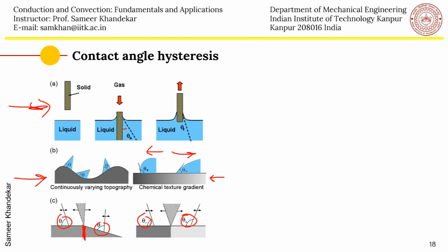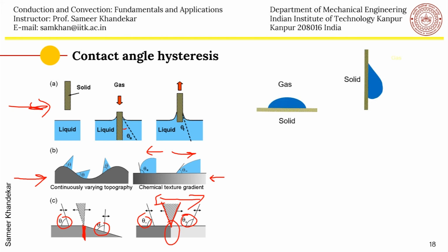So this is basically the equilibrium sessile contact angle, and on an inclined solid you will have the receding and the advancing angle different from each other, which will be theta A minus theta R. This will be the hysteresis, theta hysteresis, which will be usually observed in common engineering substrates. You have also seen such a behavior of the contact angle hysteresis.